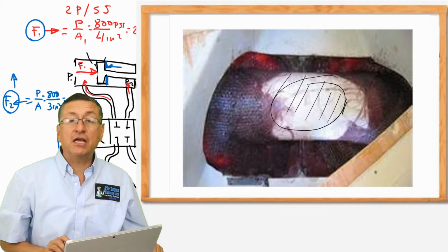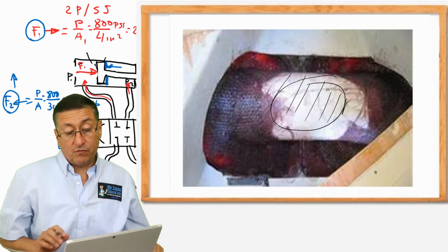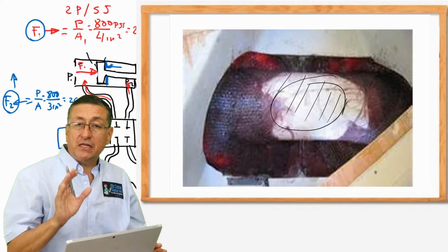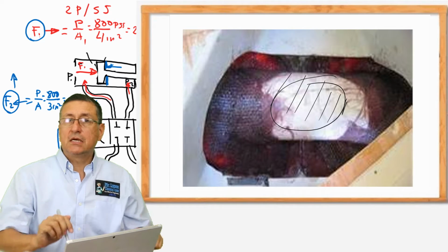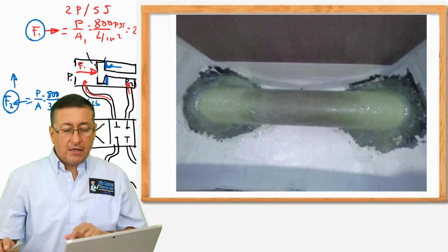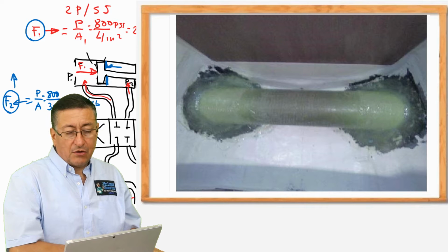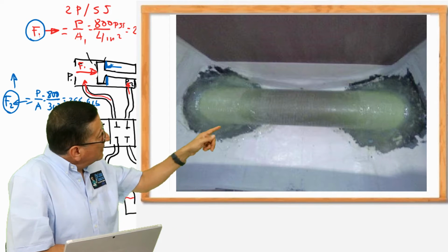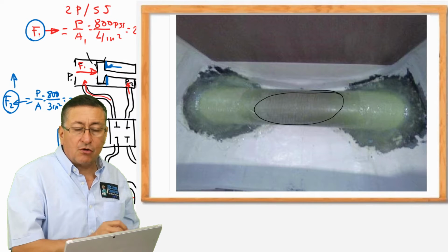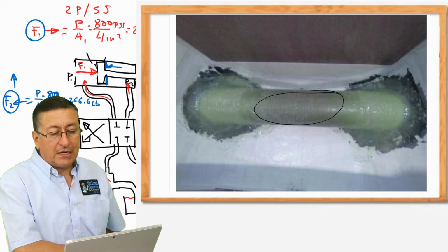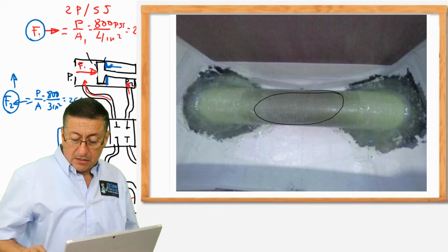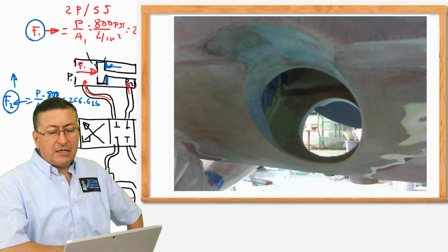This is the process of lamination, and of course, once again, try to use the appropriate resin, the appropriate mat. Try to use a professional for that job. This is another example of the tunnel and the resin on both sides. Once again, try to keep that area completely clean. Protect that area. This is a good lamination. It is properly laminated.